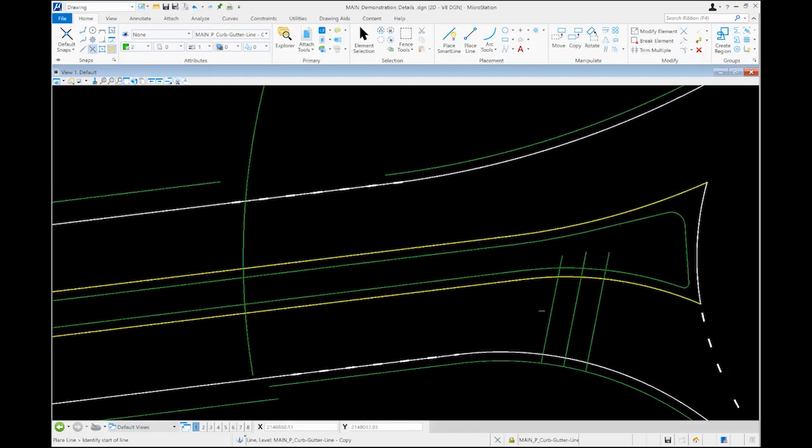So we're going to utilize the extension of these lines to about the center here, and then we'll snap to the end of that point, and then we'll snap perpendicular to the outside curb line here. So that establishes an alignment that's perpendicular to our curb line at the center of the crosswalk. And then as we offset 5 feet to either side, we end up with our angle points along the curb lines that's approximately in the middle of that splitter island as well.